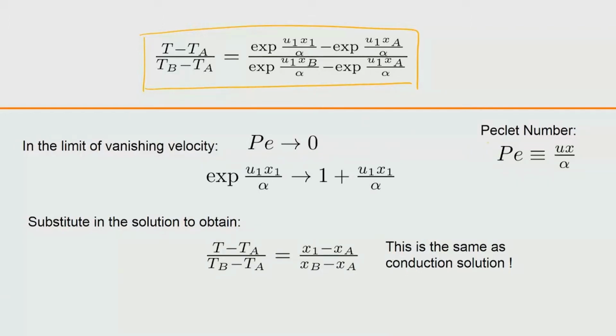And at this juncture, how the profile would look like is something where we can introduce a new concept called Peclet number. So, that is basically to look at this quantity that is appearing in the exponential, which does not have units. So, you can then think of a number for that, Peclet number. So, Peclet number is defined as velocity into distance over the diffusivity.